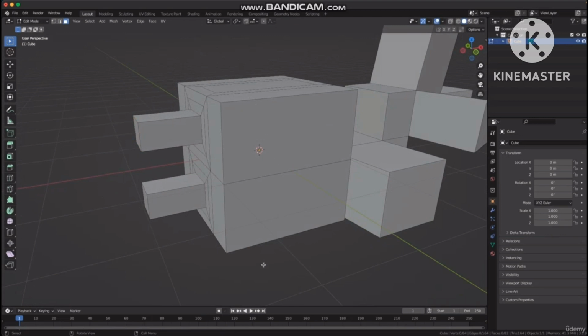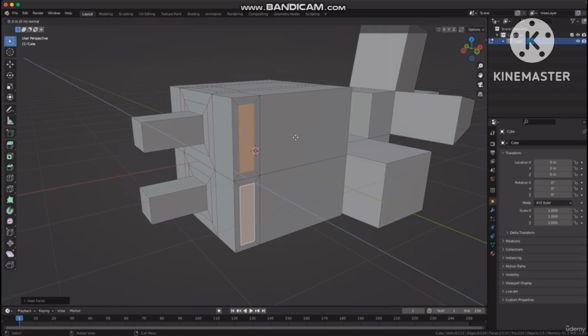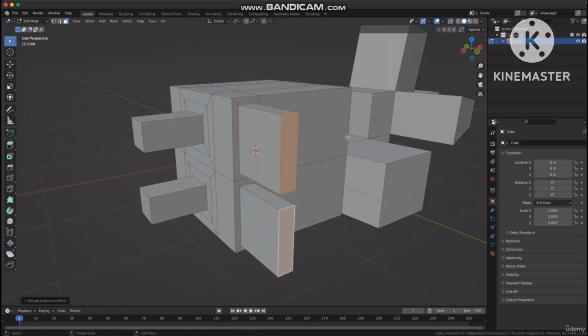So let's say we want to create a loop cut around the side of the model. So I'm going to press Ctrl R to create a loop cut. Hover my mouse pointer over the model, click, and then I'm going to drag maybe towards this area. So now I've created these extra faces. So now I can maybe click on this face and let's inset them, I to inset. And remember, if you press I again, it will toggle between one inset for both faces or individual. Now we can obviously press E to extrude and that's going to extrude those two faces.